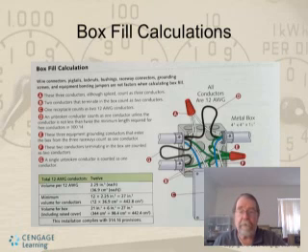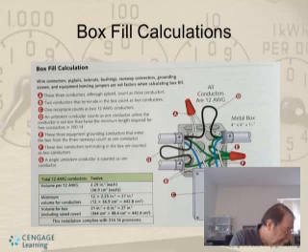Here we have a nice little example, and this goes over all of the conductors in a box. So here it goes through everything that it takes to figure out whether that box is legal. You have multiple entries into this box, so you have multiple conductors coming in and out. The 3 conductors, all spliced, count as 3 conductors.